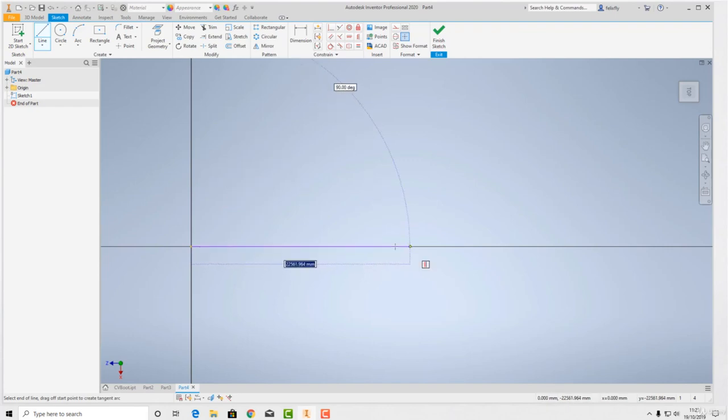I'm going to just mainly use the snapping with the mouse, and I'm going to go. So I'm going to imagine this is a kind of a duct, like an air conditioning duct or something like that. I'm going to go 10,000, which is 10,000 millimeters, is 10 meters. Okay, and then I'm going to go another 10 meters, it's 10,000, 5,000,